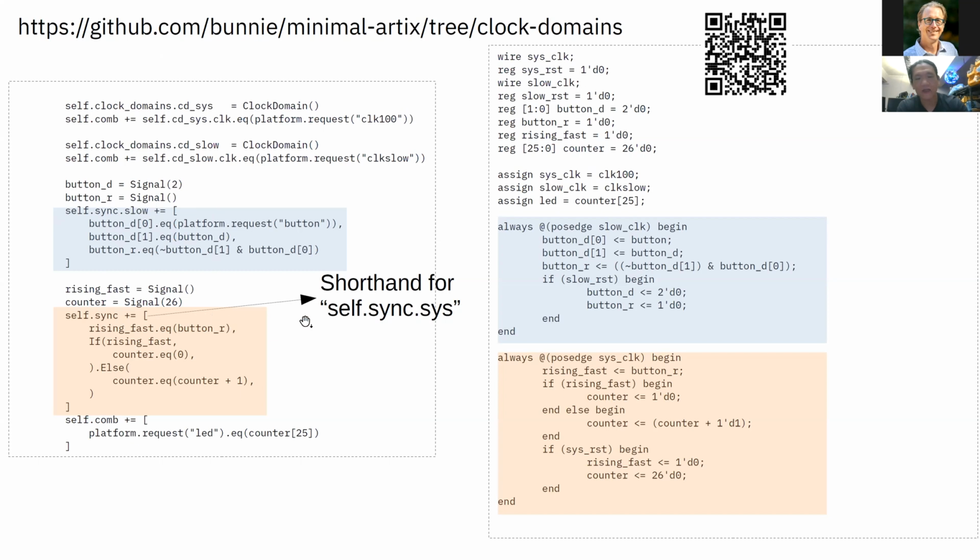And actually it turns out that, and kind of one of my beefs with the language is that if you don't specify clock domain, it implicitly drops it to the sys clock domain. And so there's a lot of this implicit, everything goes in this clock domain. So if you're not careful, stuff falls in the clock domain, and you didn't mean to do that, and it doesn't come out until you're digging through a lot of simulations. But anyways, this cleanly turns into, you can see this blue region turns into this blue region over here.